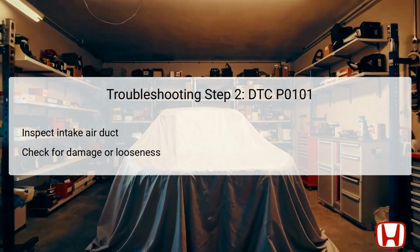The second step involves a visual inspection of the intake air duct connected to the air cleaner. It is crucial to ascertain that this component is not damaged or loose, as any leaks can lead to false readings from the MAF sensor.